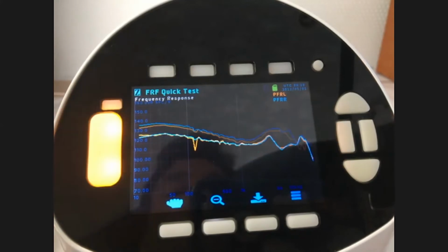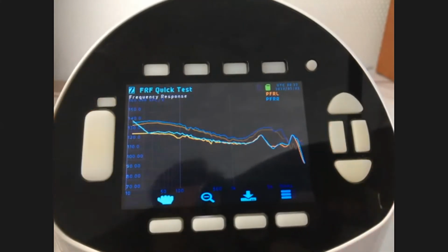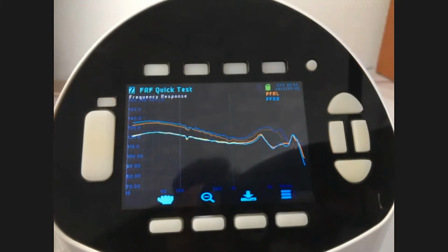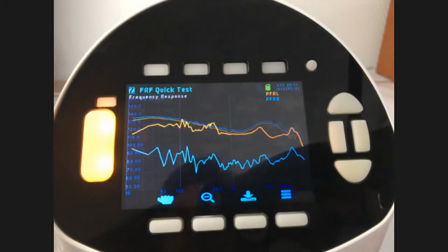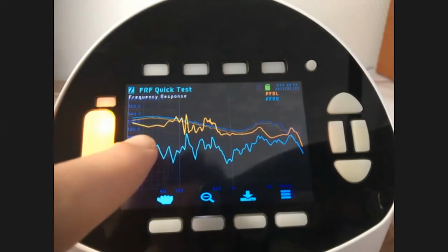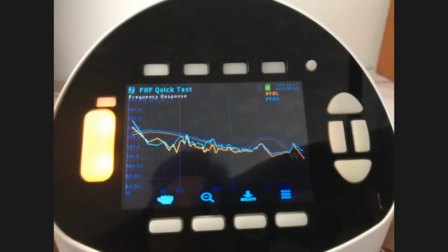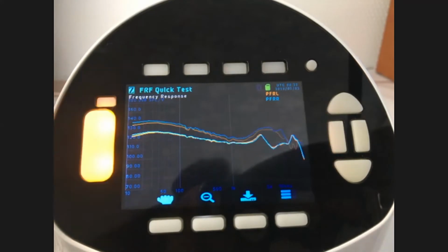So this is just going back and doing it with the same peak noise level for the other set of earbuds. Yeah, that's right. So for a frequency response, the test level, like the voltage, doesn't matter because it's always scaled to per unit volt. So they're all on the same basis. This is the SPL level if we were to use 1 volt of signal input. Now we're not, we're using 100 millivolts, something suitable for an earphone.